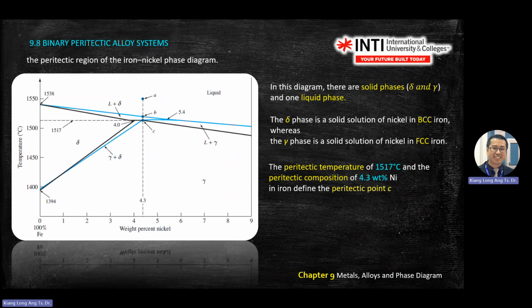As long as this section crosses to the solid, in this case point C, you extend to the left and you get the temperature. Okay. So to solve this phase diagram, usually we will ask you to write the reaction equation first, either eutectic or peritectic. Then you find where the point of the eutectic or peritectic is.